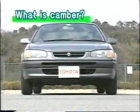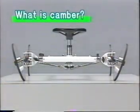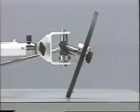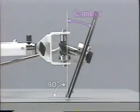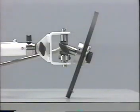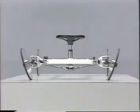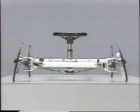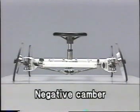When you look at a vehicle from the front, you can see that the wheels are fixed with their tops tilted outward or inward. This is called camber and is measured in degrees of tilt between the tire center line and the plumb line. When the top of the wheel is tilted outward, it is called positive camber. When it leans inward, it is called negative camber.